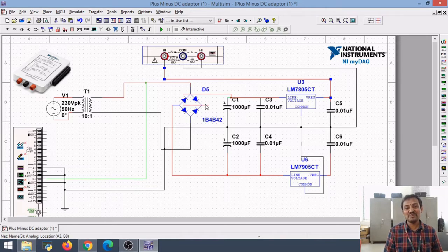What do we mean by a rectifier? A rectifier is a device which converts AC into DC. After that you have the filter circuit. Here the AC signal is converted into DC form, but it's not pure DC. It is a pulsating DC, which means some AC component is mixed with the required DC component. That AC component we call a ripple. This is an important factor while defining the rectifier.